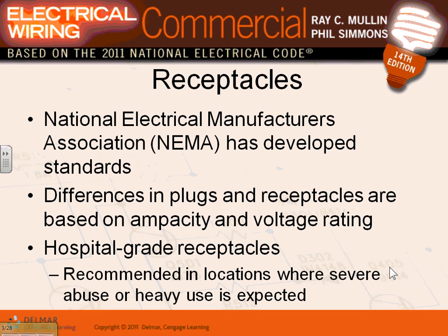So when you guys go to commercial industrial, please switch your mind. The cheap residential type receptacles that we used to do are no longer approved in any engineered project. Can I use them by code? Yes, I can. I can use a residential 33 cents receptacle anywhere by code, and that's okay. But on engineered projects, 99% are going to ask for commercial grade receptacles, more robust, or hospital grade receptacles. So we'll talk about these guys in a second.